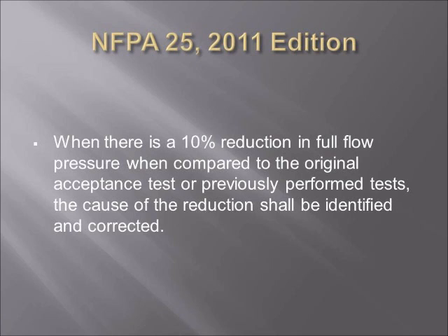Ideally, as a building owner, you'll have the original above-ground contractor's material test certificate that was provided to you when the system was first installed and accepted by the contractor and local authority having jurisdiction. This documentation has the first main drain test that has been conducted. The reality is this documentation is quite often misplaced and not usually available. In the absence of this, main drain test results should be compared to the previous year's main drain test results.